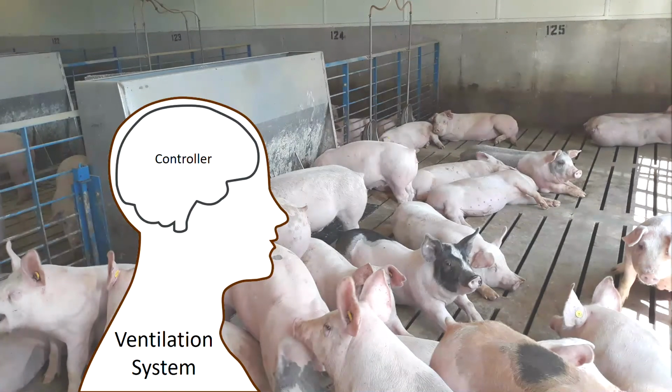While some more sophisticated controllers may use a variety of measurements to make decisions, temperature is the primary measurement that influences ventilation control settings. The ventilation control system is a computer and uses a temperature probe to sense what is happening in the room environment. The controller then makes decisions based on the probe temperature with respect to a set point.